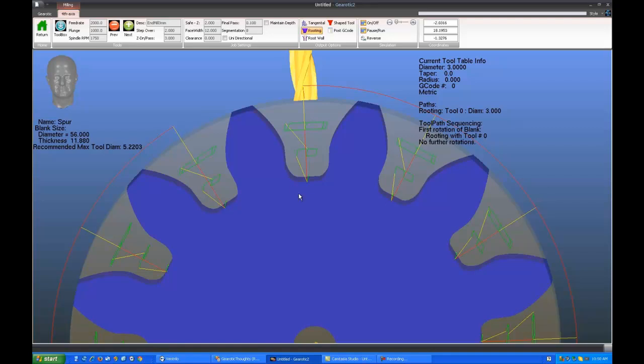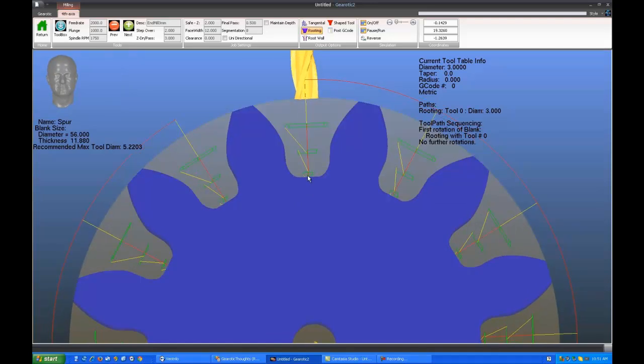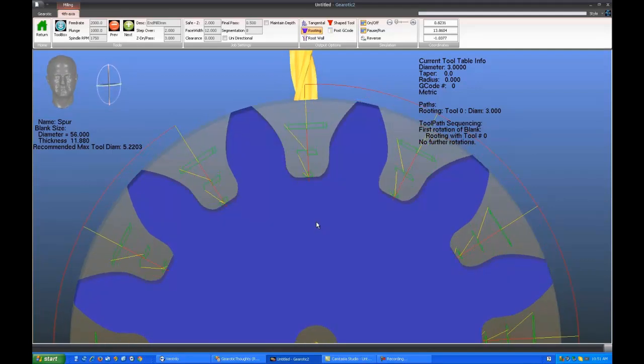So this bottom pass, you may want to get more than the one pass on it. It can help to give a final pass. If I put a final pass of 0.5 millimeter on this, because the 0.5 millimeter takes us above this curvature of the graphics, we actually get an extra little bit of a pass on either side for a more efficient clearing. So you might want to consider having a bit of a final pass. In the end, it can make a bit of difference as to whether or not the trochoidals are cleared out enough for you.